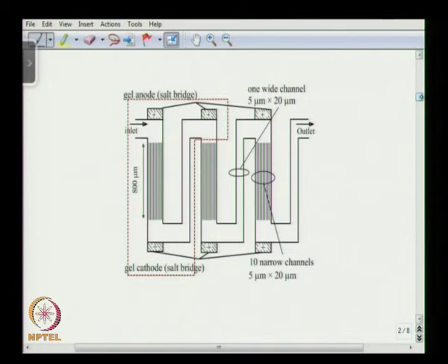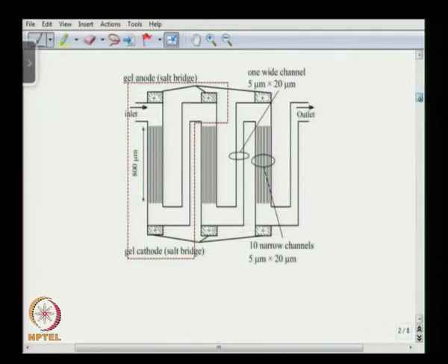If you look at here, we are considering a cascade electroosmotic micropump and we just try to consider a single stage enclosed by this dotted line. For a single stage, the first part of the channel is divided into many small channels such that the pressure capability is more, and the second part of the channel has a large size, so that we obtain larger flow rate. So let us analyze one such stage here.